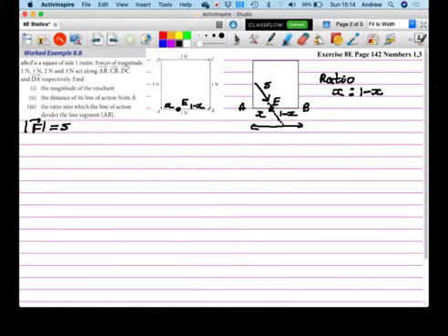So, how am I going to do this? Well, this time, this is a trick question. When they ask you for something like this, you see where it cuts the line in question, and that's where you take moments about. So we're going to take moments about E. And again, I'm going to choose to take moments in the positive direction.